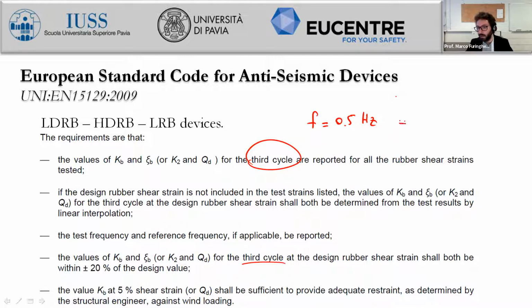And so according to the frequency and according to the assumed maximum displacement, we can compute the maximum velocity, which is equal to 2 pi times frequency times maximum displacement. So this will be the key value for the velocity time series. Generally, when we have to carry out tests in a laboratory, for instance, at the Center Foundation, we have to provide all the characteristics for the test, that is the waveform, so sinusoidal, the frequency, the maximum displacement, and the velocity.